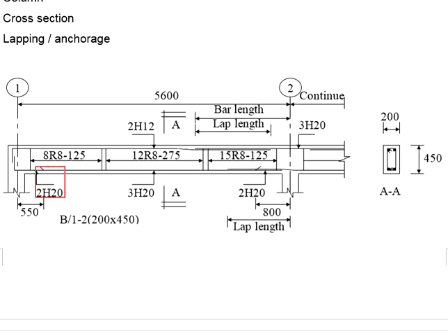Now settle the curtailments here. Settle the reinforcement at the support. You will need to consider also the reinforcement from the adjacent beam. Do the calculations for the midspan of the adjacent beam, get the amount of reinforcement, and then see if the size of the reinforcement is similar to the one here. This is of course after the curtailment.